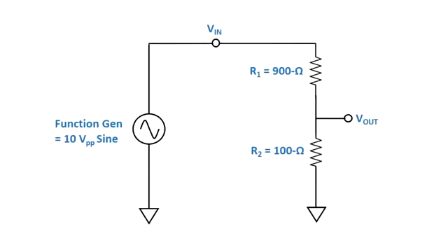In the simple 2-resistor resistive divider circuit that we've been making measurements on in some of the earlier lessons, the gain and phase of this circuit is constant across all frequencies, at least ideally. The transfer function of this circuit is simply R2 divided by R1 plus R2, which is an absolute gain of 0.1 and phase of 0 degrees. The logarithmic gain is 20 times the log of 0.1, which is minus 20 dB.